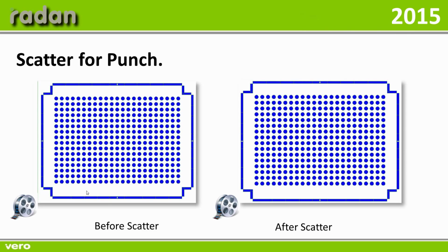Okay, now let's look at that same program ordered with the scatter command enabled. And on this example, I've actually used the shape code of 1. And as you can see, that will then allow me to move diagonally, but also jump 3 sets of holes. Now this is going to spread the stress in the sheet out across the sheet, helping us avoid deformation in the sheet.